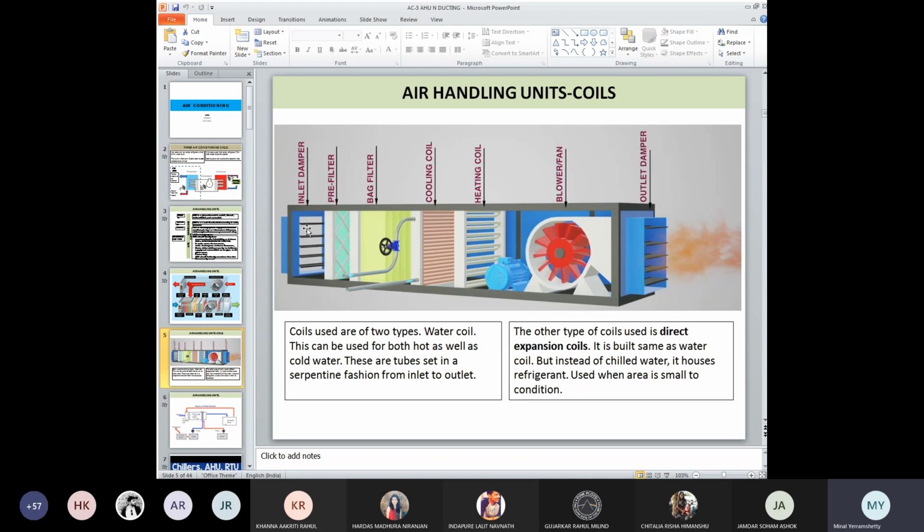है ना? So how do I stop the smoke? First of all, I seal the room. So my door has to be such that it is not allowing the smoke to come out. That is one thing. Second, the duct is the usual way the smoke passes. So the other thing I have to take care of is that I seal the ducts, and dampers work for that.